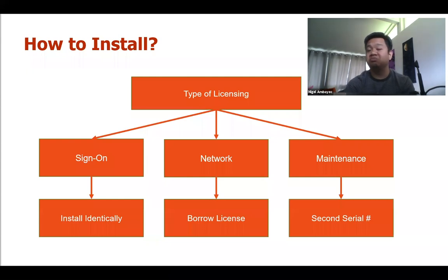Essentially, you use the borrow license, which is in the same dialog as the about that we had earlier, and you borrow that license for a period of time. Now, if you don't borrow it for a period of time, the default is quite lengthy, so definitely keep in mind about that. You can also limit the amount of borrow time or who can borrow via an options file on your license file.